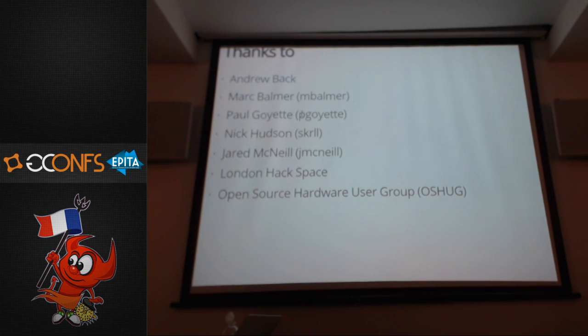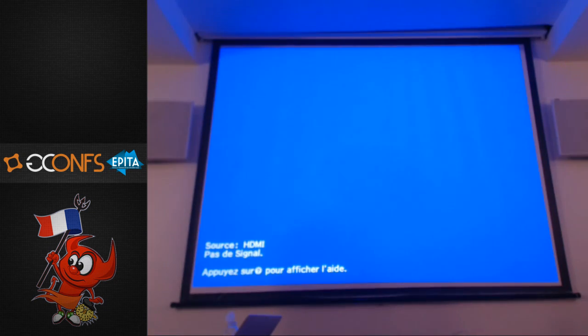So basically, someone in the Pöttering land decided that all serial devices are obviously modems, and they always send some AT sequences to it to try to get it to talk back, and it's especially annoying if you're dealing with FPGAs you want to program, but it can also mess up any other use of serial consoles. So this is just a service announcement. Be warned.